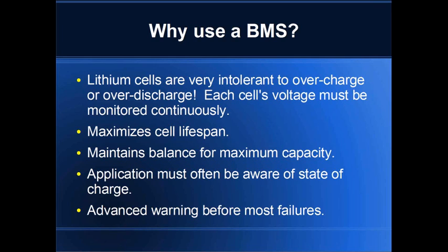And so what ends up happening in that situation is that you charge up and you get one cell that maybe won't even turn into a more serious safety issue, but the cell might get just a little bit overcharged, and that's going to shave life off of that cell. And then when you discharge the battery pack, you're going to have one cell that gets just a little bit over discharged, and that shaves life off of that cell.